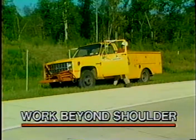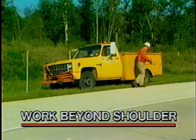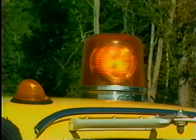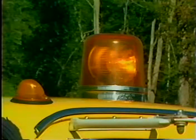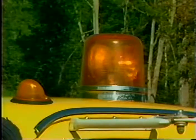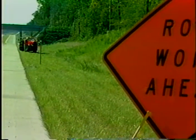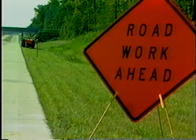The best way to illustrate these principles is to show the installation of the control scheme for some common types of operations. In the first example, the work is entirely beyond the shoulder or parking lane. Traffic control will generally consist of flashing vehicle lights and flags. An advance warning sign should be used when the work will interfere with traffic in any way.